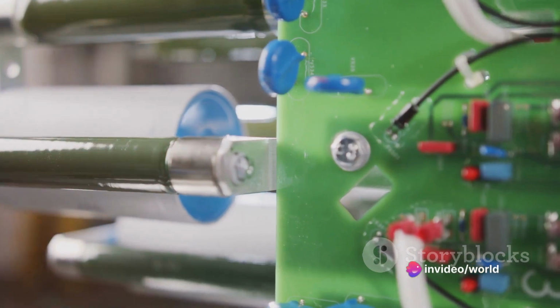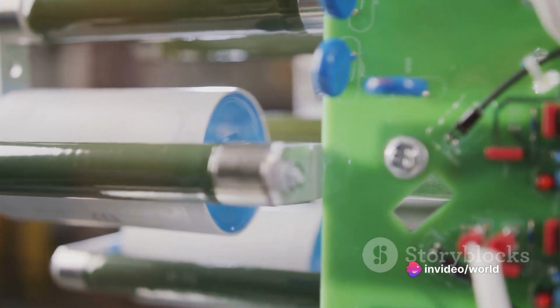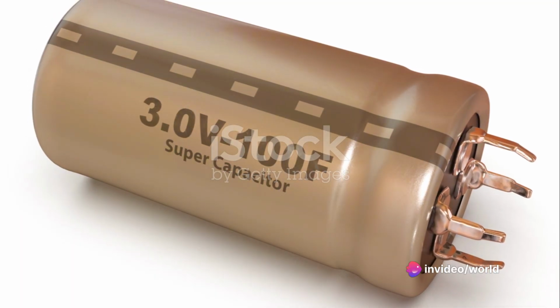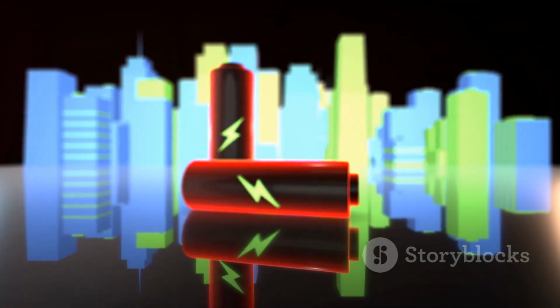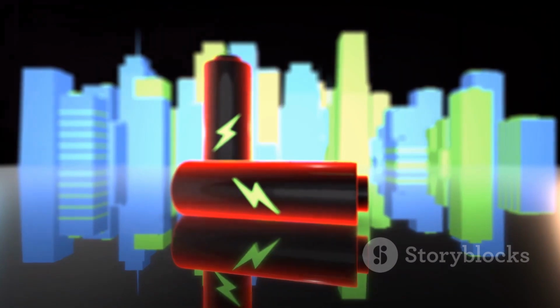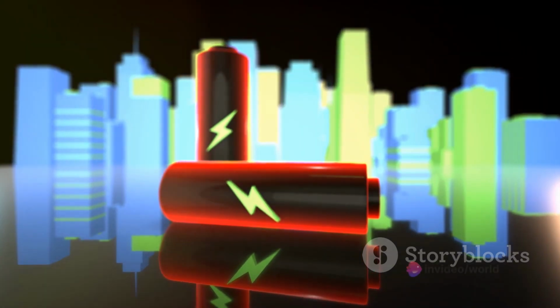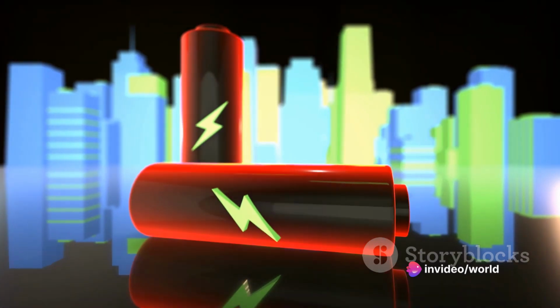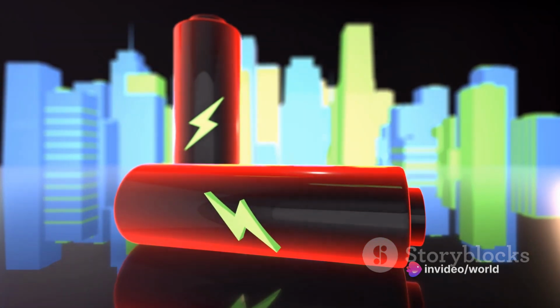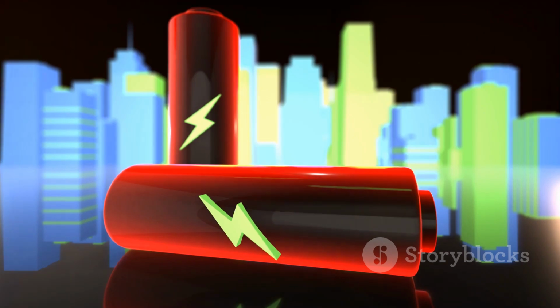The secret lies in something we call capacitance. Capacitance is the ability of a system to store an electric charge. It's determined by the physical characteristics of the capacitor, specifically the surface area of the conductive plates and the distance between them. The larger the surface area and the closer the plates, the greater the capacitance.